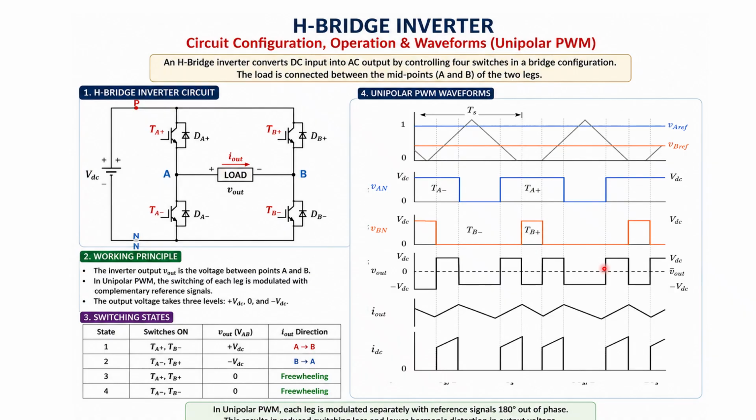The reference signal for leg A is compared with a triangular wave to generate the switching sequence of TA plus and TA minus.